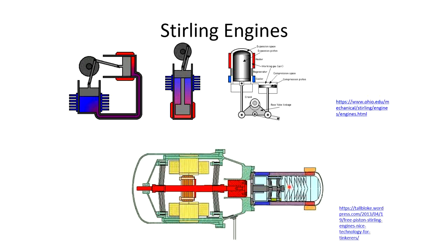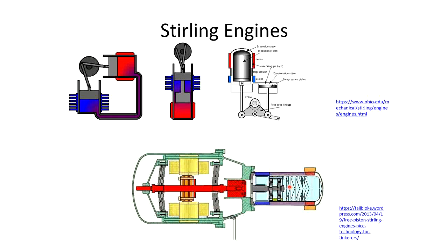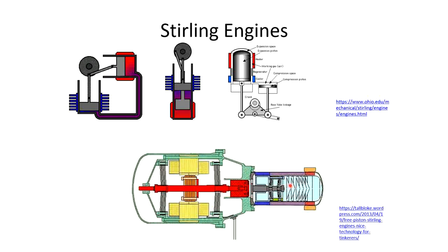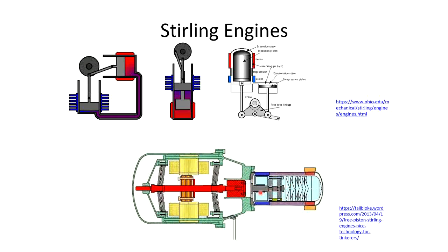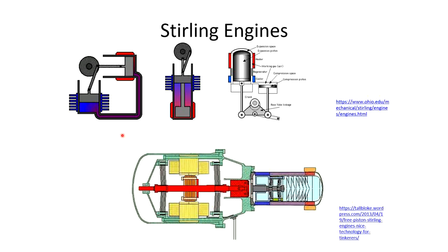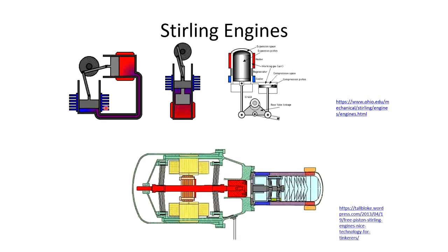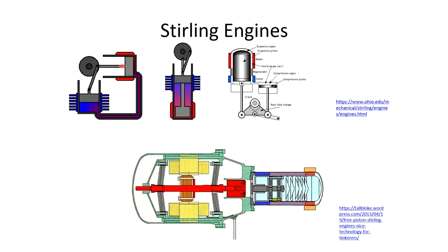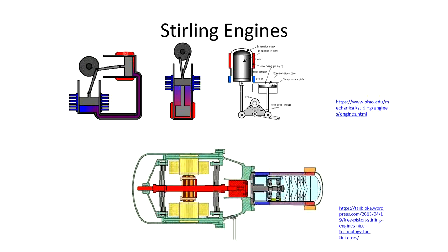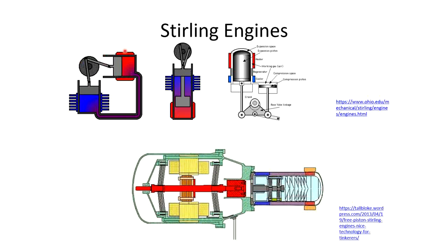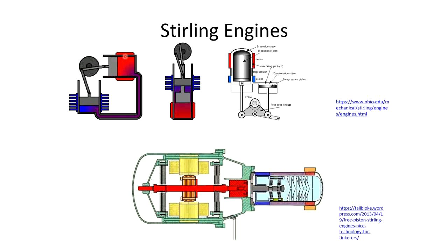So now let's see in detail how the Stirling engine actually works. How is this cycle realized, or how do we try to build systems with the Stirling cycles? Typically the Stirling cycle can be made in so-called alpha, beta and gamma configurations, where here in the alpha configuration we have 2 pistons in 2 separate cylinders, the hot cylinder and the cold cylinder. Into the hot cylinder we have the heat addition.